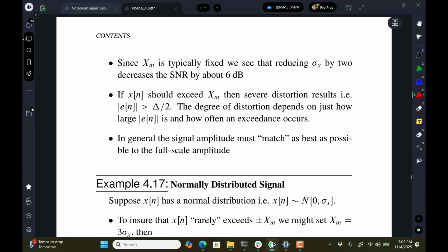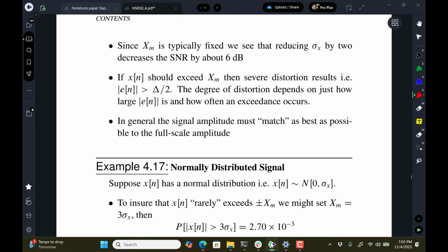This was exactly what audiophiles were saying was wrong with the compact disc. They were saying when the compact disc came out with its 16 bits, that quiet passages of a symphony, the gain would be set constant so you could handle loud passages, so the really weak passages would get lots of quantization error on them, and that was going to be noticeable. There are still people that I think believe that to be true, and it probably is to some extent, but what are you going to do? If you start automatically gain leveling everything, then you compress the signal and that distorts it too. So you have to just come up with a happy medium.